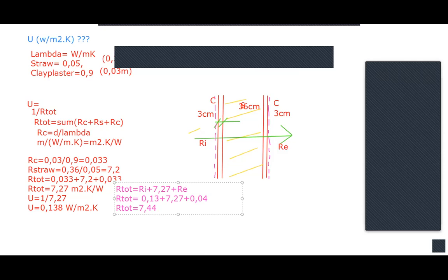Okay, but this is totally unrelated to the type of wall you're building. It could be a brick wall or... Yes, anything, exactly. Perfect remark, thank you. If it is a wall, it's there whatever material it is built from. It is the same for a roof. It doesn't matter if there is a cladding or clay plaster or whatever. It's on every construction. So that means 0.13 is always for the interior side and 0.04 from the outside.